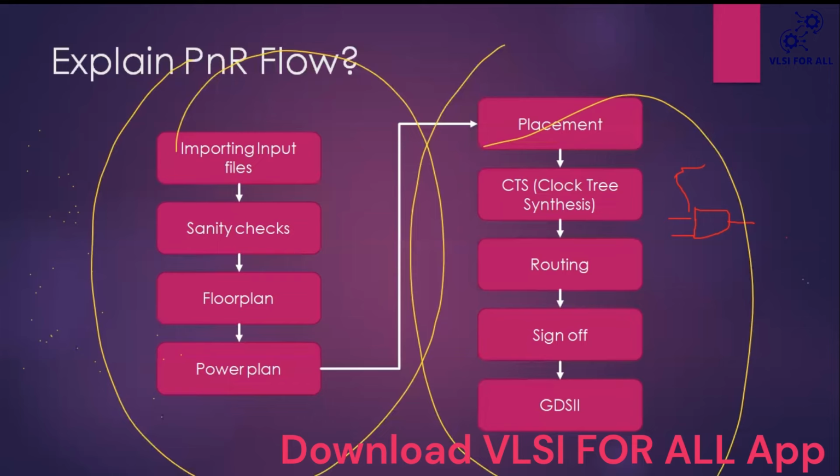The flow is: power pads to power rings to power stripes, from stripes to S routes, and from S routes to standard cells. You will see this full flow in top level designs only. In block level, you see only power stripes, S routes, and standard cells.